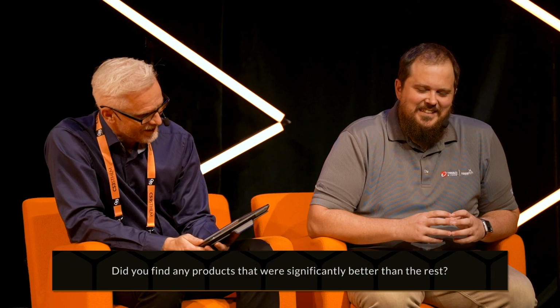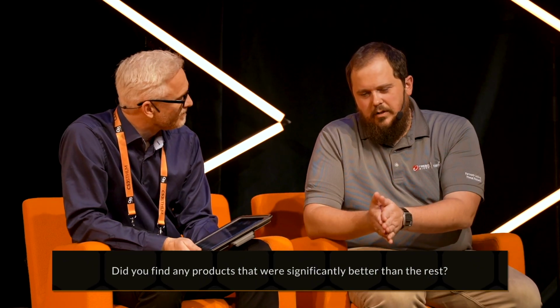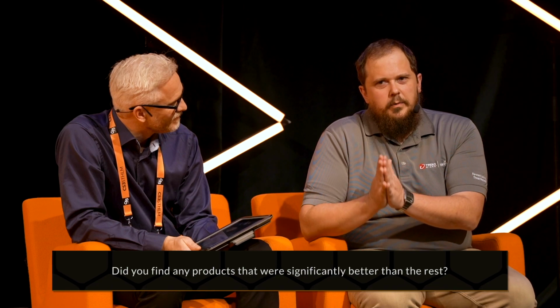Simple answer, okay. So as I said, with the JUCO, we were really hoping that when we couldn't see the commands, something was going on to help protect it, but we had several of our teammates going, oh, this has to be encryption. And I said, but a replay attack works, so it's not encryption. Something else is going on. They're just trying to mask something. And it turns out it's to really help with the pairing. That way you can actually receive the packet, decode it with the pairing code, and then you have a command.